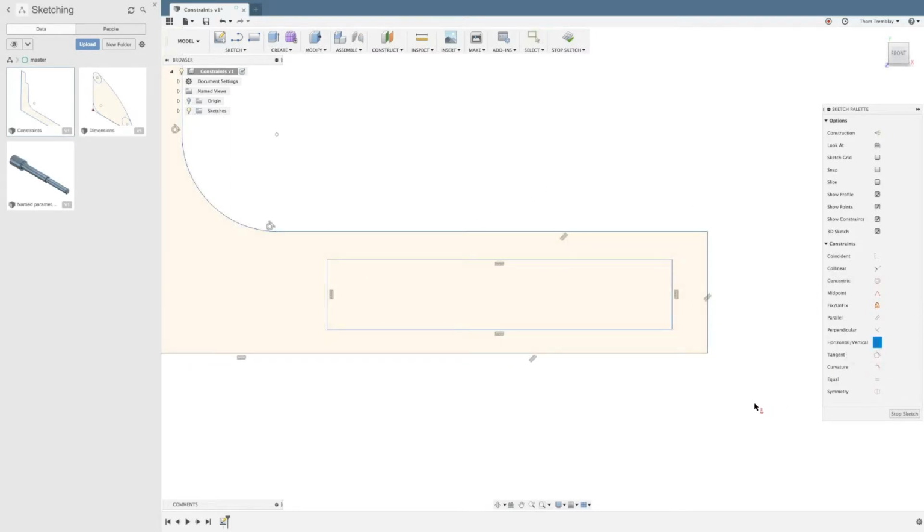This is a great use for horizontal vertical. Now, as I move over this line, you'll see that no midpoint is presented. To get this to work, you have to hold Shift. This will present the midpoint. As a little tip, it will put these icons near their midpoints for the most part. Okay, and we'll come over here, find its midpoint.